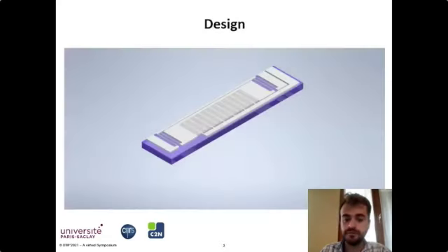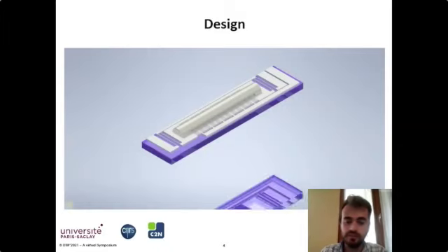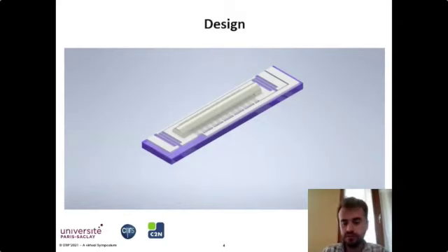So here's our device. It's made on a silicon on glass wafer to avoid parasitic capacitances. And we are going to add a tungsten mass in order to bring down the resonant frequency of the system in order to match the spectrum of the heartbeat. Once the supplementary mass is on the system, we're going to add a second device that will, instead of moving in the vertical direction, move in the perpendicular, horizontal direction, in order to use these two movements of the heart.